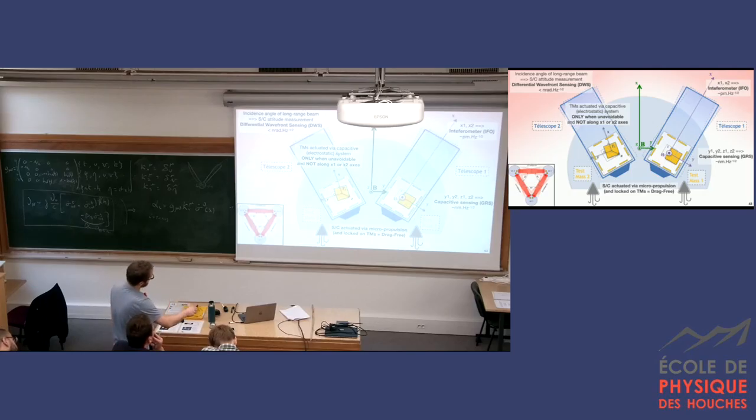If you do an asymmetric imbalance between the electrodes, you can apply torques and make it rotate. As I said multiple times, you certainly don't want to apply any force on the axis here. But because you have optical metrology systems here and here, on this axis and this axis you never apply any force on the test mass, but you can translate the spacecraft. You can correct any motion seen by the two test masses.